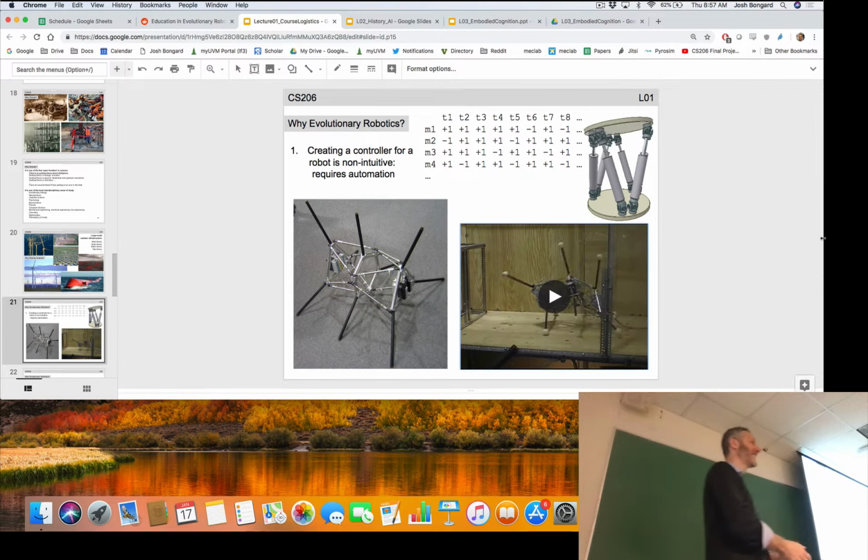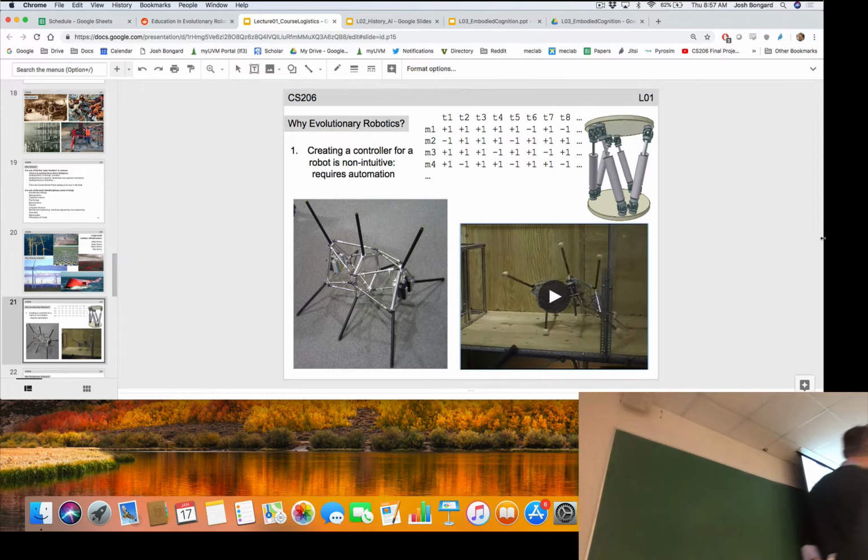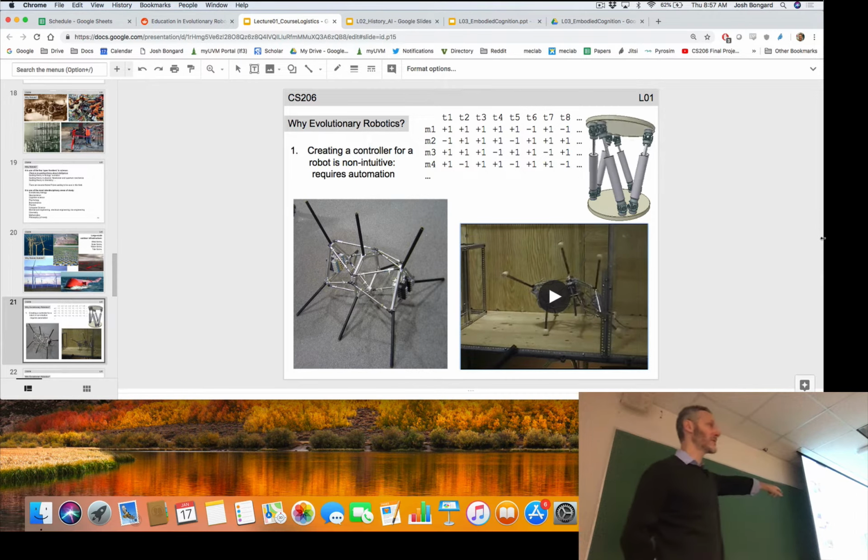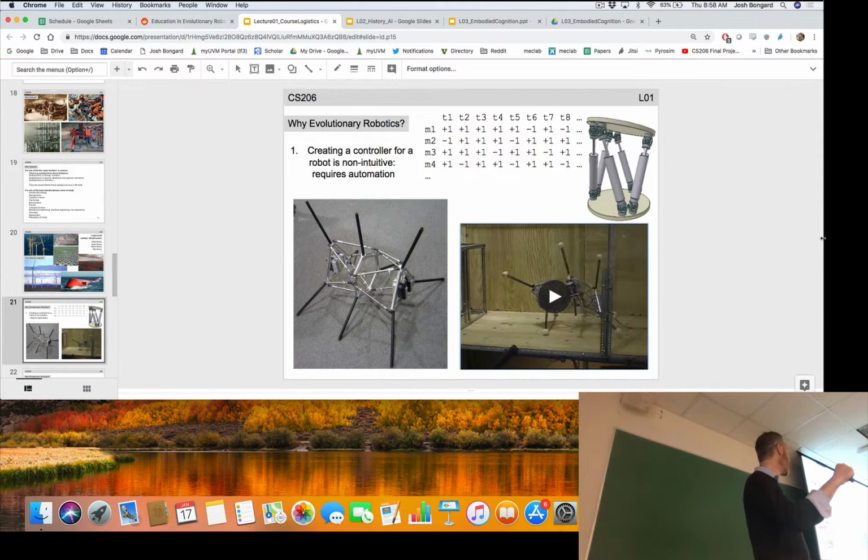Okay, question. So why do you guys choose balls as the place of contact? Okay, so those are rubber balls because we were using carbon fiber for the legs. That black material is carbon fiber, which is relatively rigid. You can see that this robot is pretty strong. Without the balls, it would smash itself to pieces in about an hour. So it's just to absorb contact.